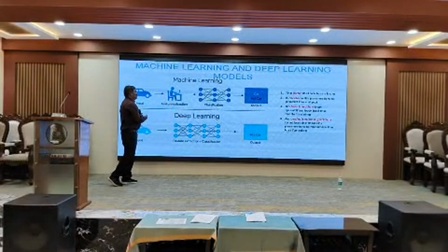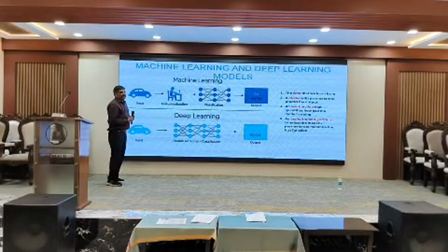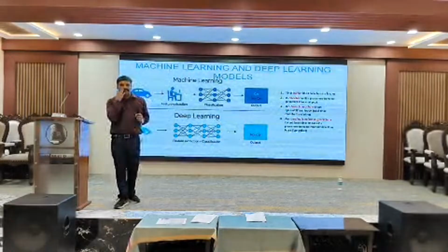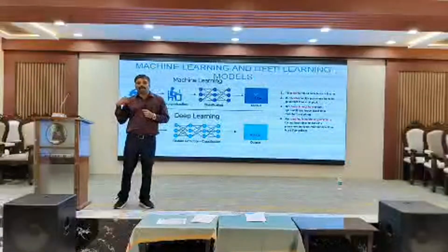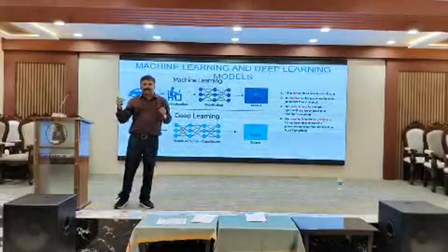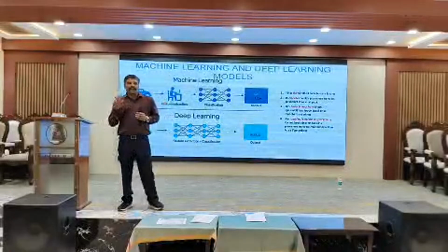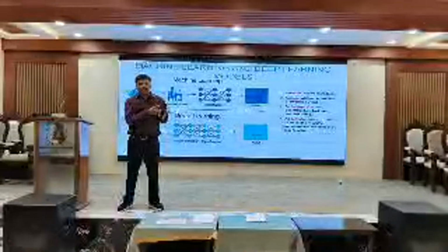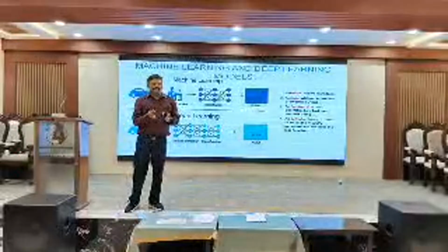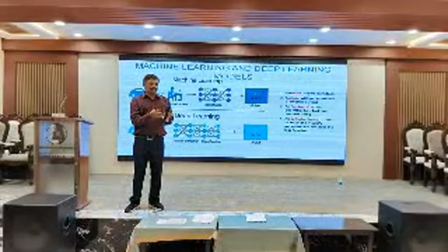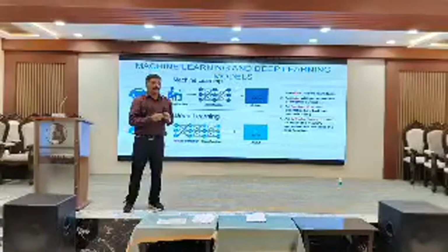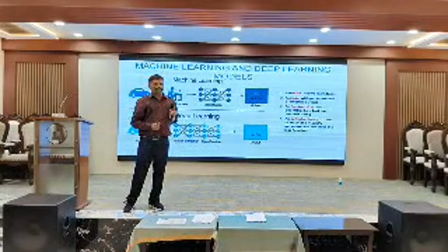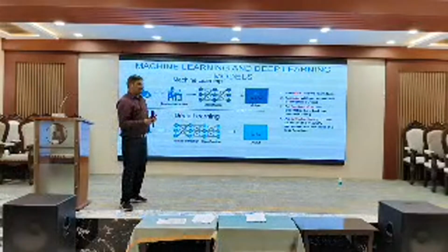But here in machine learning, you have to do some pre-processing. That's called feature extraction. That means, say you have a gearbox equipment. You are trying to put an accelerometer over there and you are trying to get a response over it. If we take a response of the signal, if you measure for 1 hour at the rate of say 1000 hertz sampling frequency, that means for 1 second we are going to have 1000 samples. Even for 36 seconds it's going to be 36,000 samples. For 360 seconds it's going to be 3,60,000 samples. So the size of the sample is going to be very large. For a single sample itself, the length of the input is going to be in terms of lakhs. The dimension is going to be in lakh.